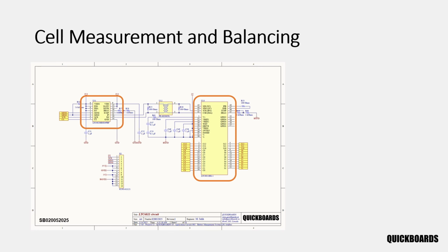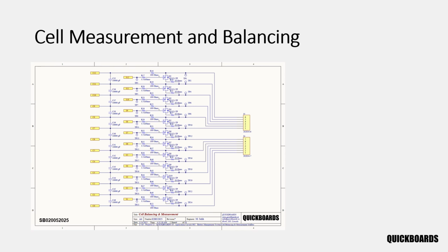These two chips communicate through a pulse transformer, keeping the battery pack ground electrically isolated from the rest of the system ground. The LTC6811 measures cell voltages through pins C0 to C12 and controls cell balancing using pins S1 to S12. The second schematic within the power management block includes two key circuits, an RC filter for cell voltage measurement and a P-channel MOSFET used for cell balancing.